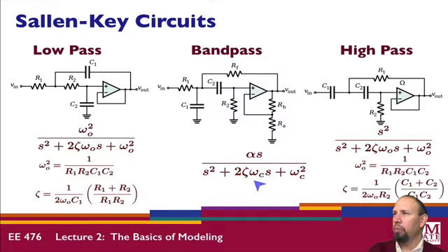For the bandpass, again, we get complex poles. Notice that we have a 0 at the origin. This gives us something like what's called a rooftop filter. At zero frequency it starts at zero, then it goes up, and then it breaks down at omega c.